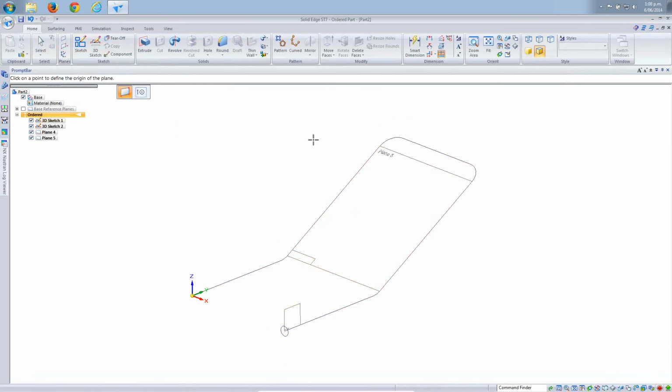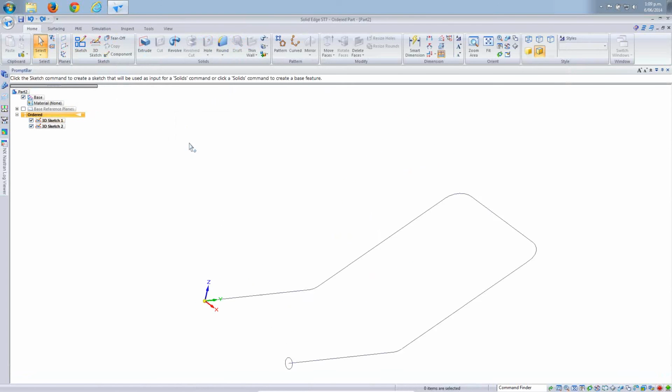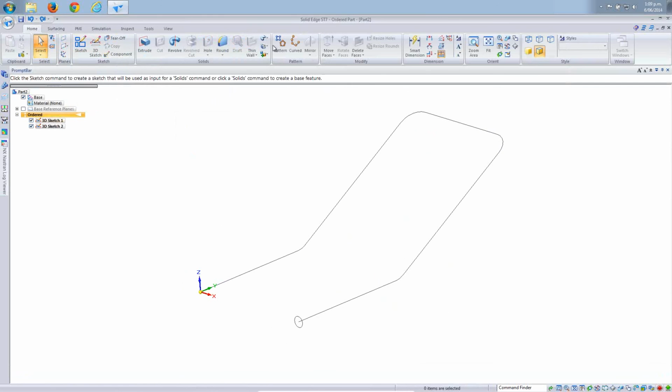But I would have had to create a sketch on this plane, and those three lines there, or the line and the two arcs, I'd have created in a further sketch. So that would have been three sketches created for the sweep, and then the cross section as well. So here I'm able to do a couple of undos and get rid of the planes. I'm able to do all of that in one single sketch, and that is a significant time saving that I'm getting from that. We'll add in our sweep.